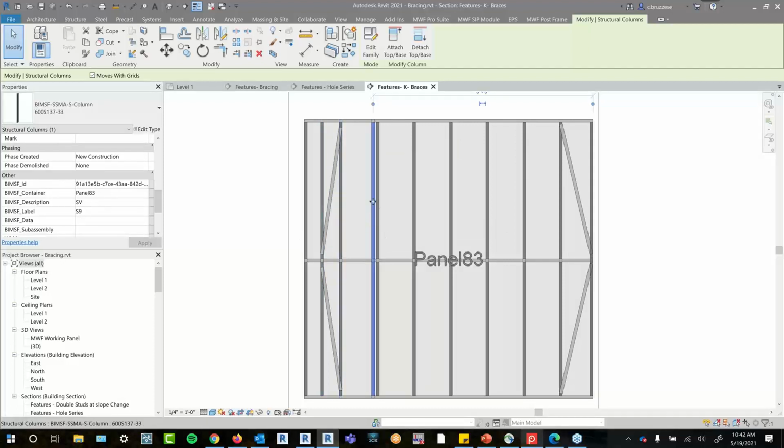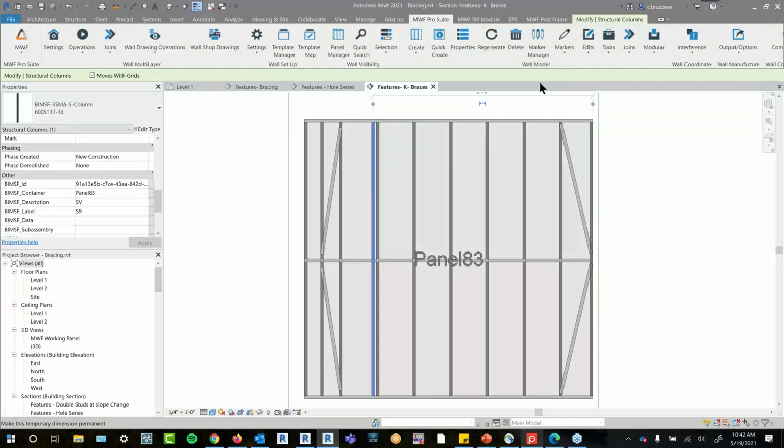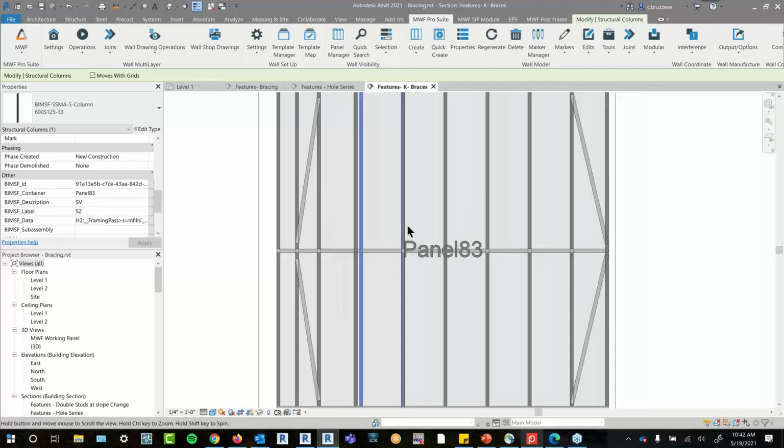I would try adding in a member just within extra studs if you can, or even as a stud pack, basically just something that isn't pinned. Might be an issue with the pinned piece is all I'm thinking. But in theory, whatever member you add in, as long as it appears on that list, it should consider the bay. So it should behave like this. Not sure what happened the first time around, but that's exactly how it should behave. If I can't get it to consistently appear, I can put it in as a bug for you.